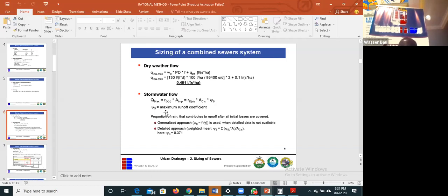If you break it down, it also means the rain intensity times the total catchment times the peak factor. So these two are just the same thing. It's either you write it this way or you write it this way. If you're writing it this way, you must multiply by the peak factor. So if I multiply this times this, it will give me the impervious area.